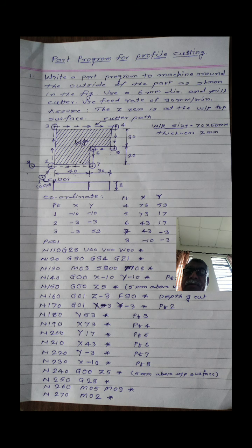Is it okay? Do you understand how to find out the coordinates? While finding the coordinates here, you have to consider the radius of the cutter. After finding the coordinates of the points, you can write the program in a similar way as in the case of drilling operation or lathe operation. That is the first program for profile cutting.